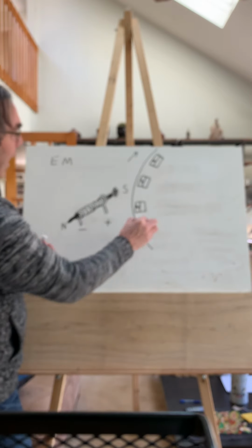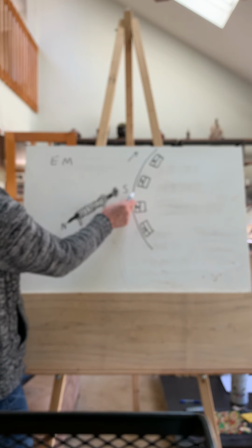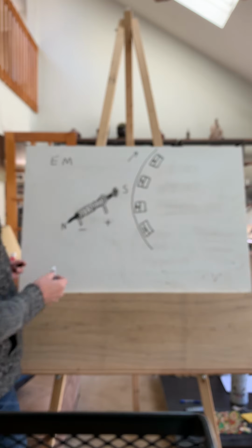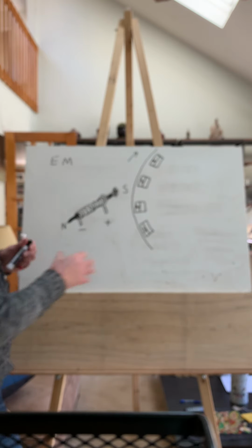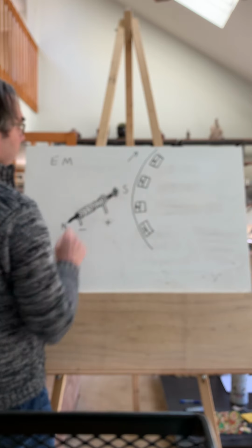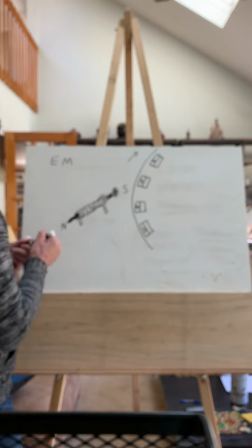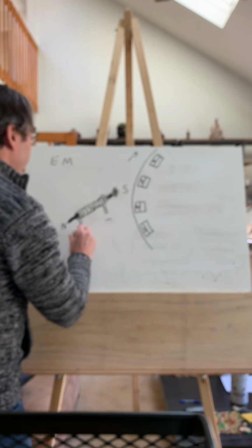south here, right? As this is turning, this south pole of this electromagnet is going to attract that, and then it's going to be pushing that south pole away. And so this thing is going to rotate up here, right? When that north pole reaches right here, right in front of that, we're going to swap the polarity.